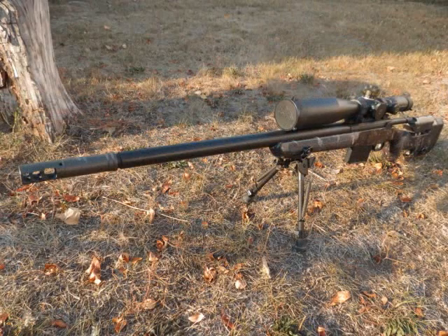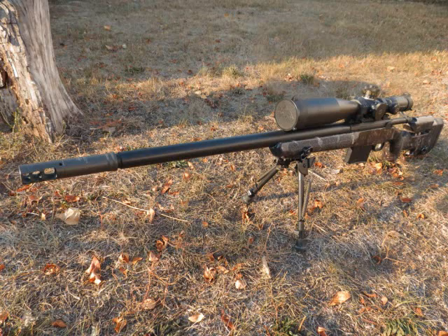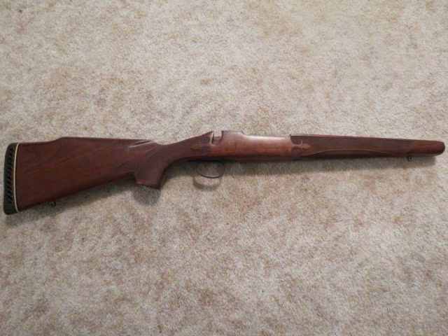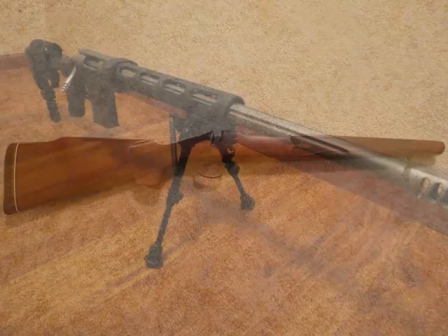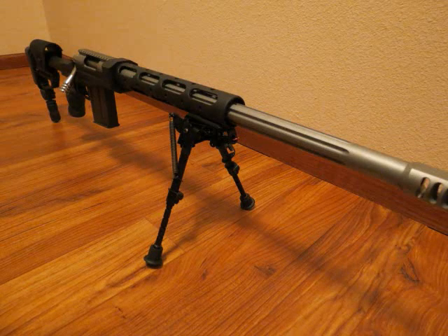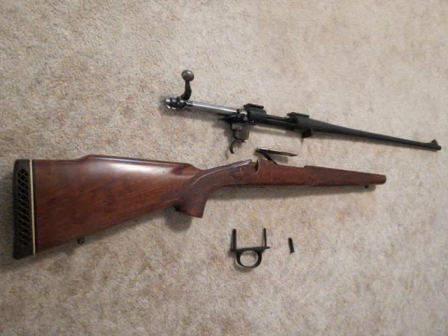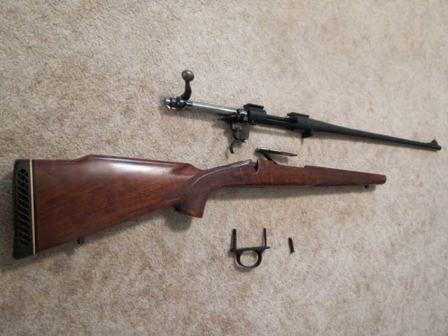The other way to solve this problem is what they call free-floating the barrel. And that's where you remove enough material down the stock channel to where your barrel can basically ring freely. It can just vibrate all at once, and it's never going to touch the stock forward of the receiver. And what that does is allow consistent whip action. That's actually probably the more common way of addressing this problem, and that's not too hard to accomplish at home. I'm not going to show you how to do it here. There's a million videos probably showing you how to do that.